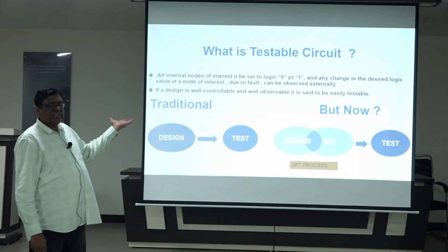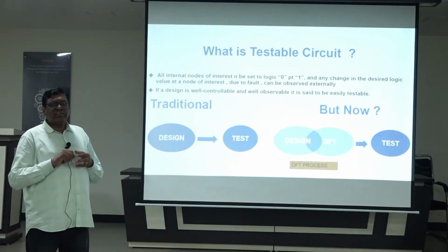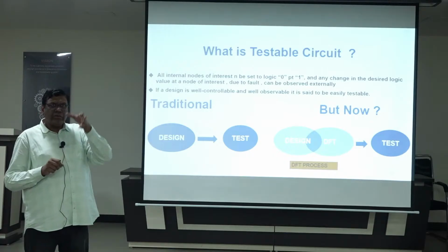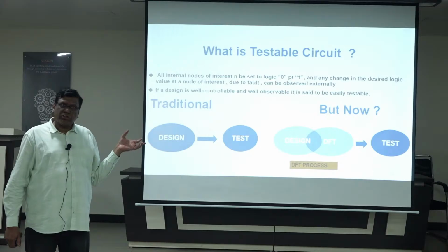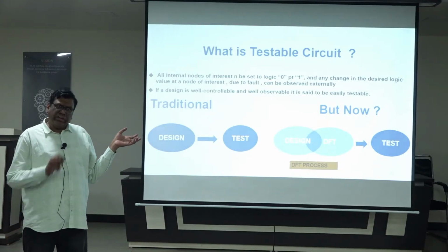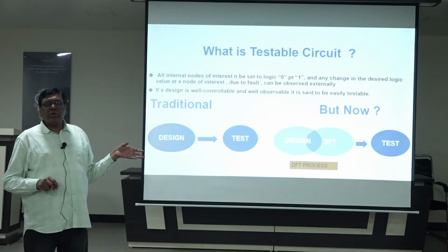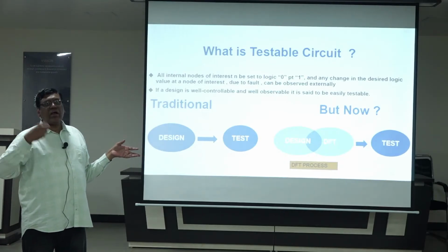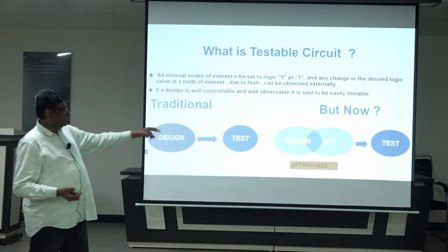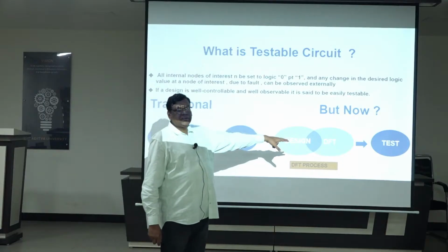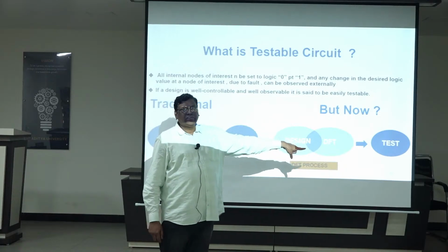So maybe in the previous example you can directly set it, but if it is very deep in the IC, all the inputs are not directly connected to the primary input of an IC. Is it possible to set it? Somewhere deep in the IC it is there, and I want to set it by inputs. Is it possible? No. We have to add some hardware to make it settable. That hardware is nothing but what we call DFT. Along with the design, only if you keep DFT is it possible to test it.